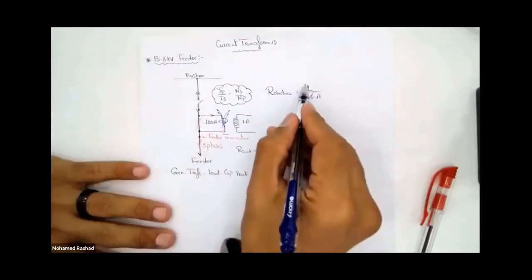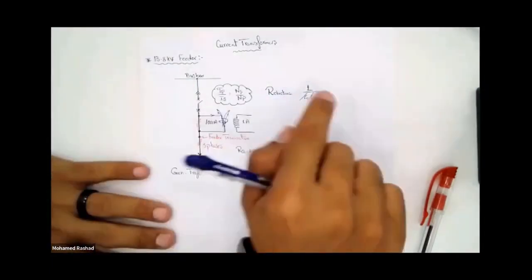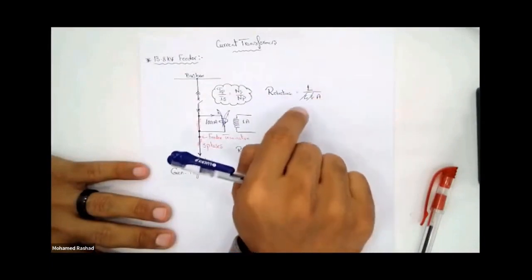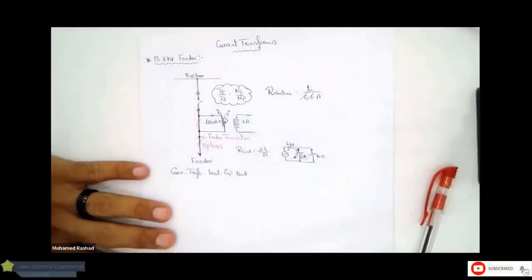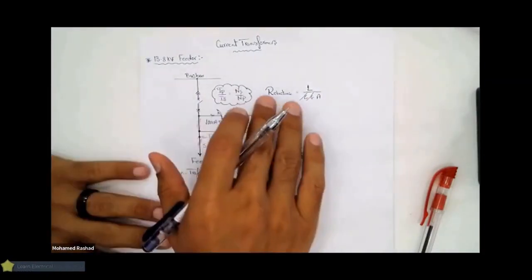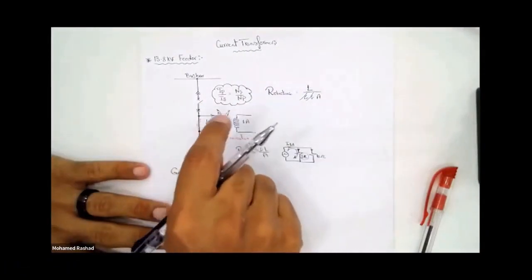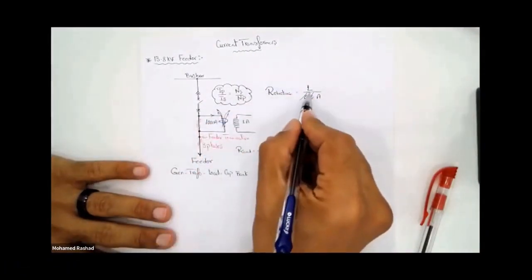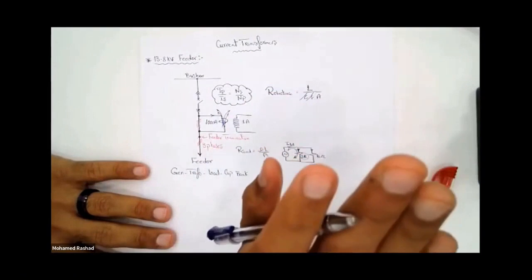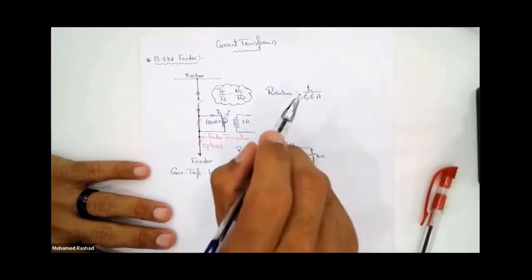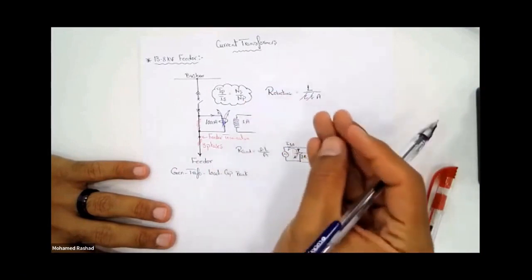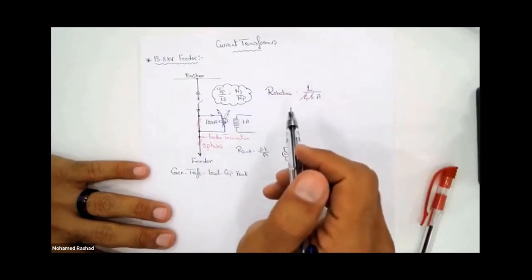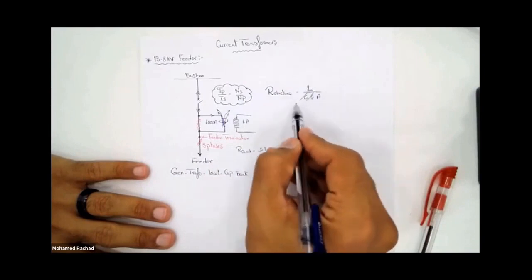All right, so the L is the path length that it will travel through, and you have A as the cross-sectional area, and mu naught times mu R. What is mu in general? Mu is what we call the permeability, similar to permittivity. The basic idea here is that now you have air, and its mu R is considered to be 1. So the air has resistance, or reluctance, to the flow of flux lines. This reluctance equals L over mu naught times the area.